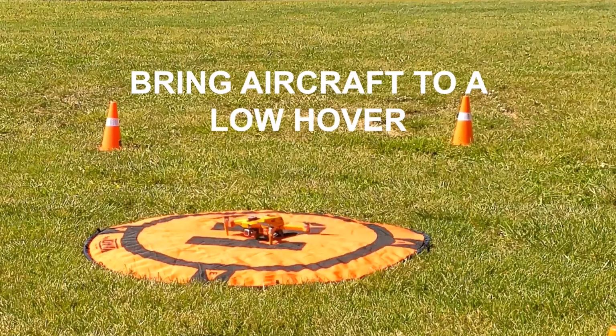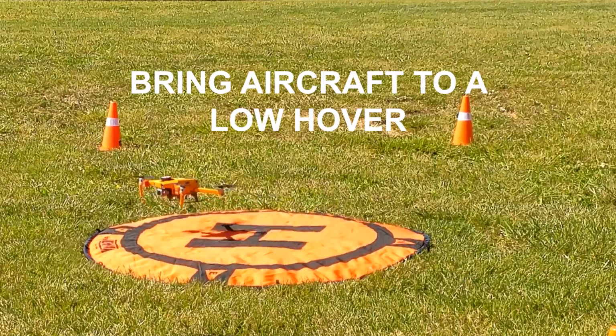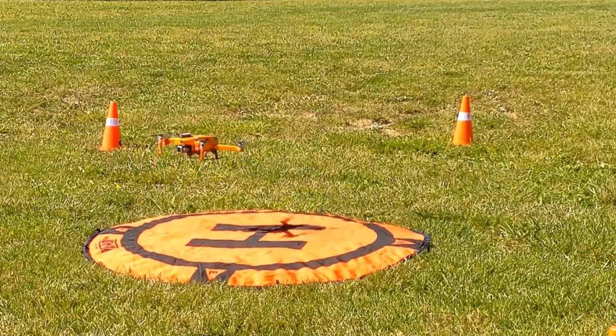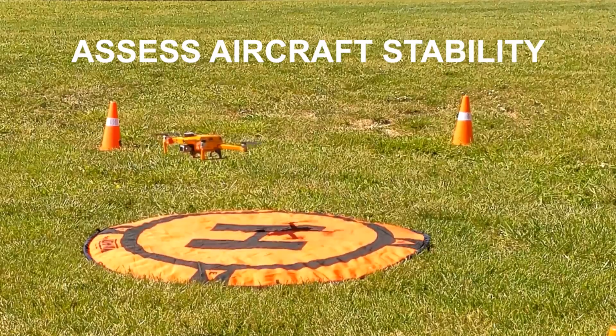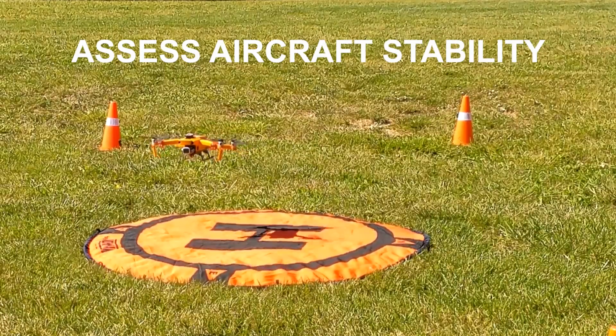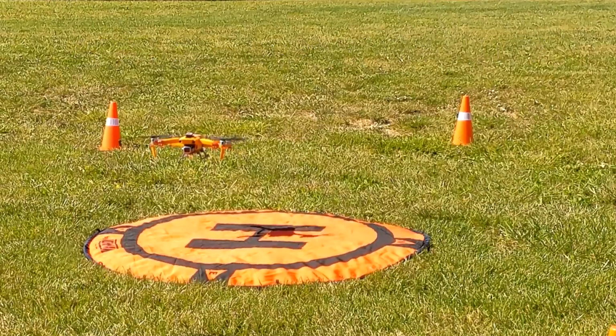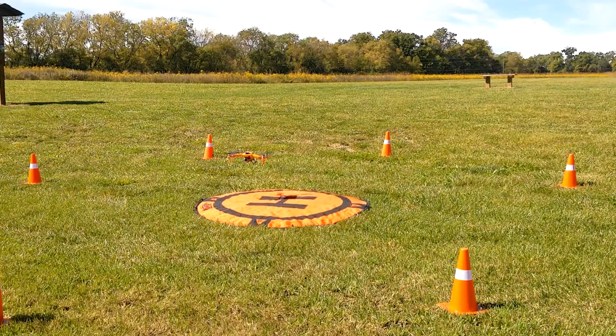Next, you want to lift the aircraft off the pad and bring it to a low altitude hover between 2 and 3 feet. Just allow it to hold its hover and assess whether it's stable or not. The drone should be able to hold its hover with a great deal of stability.